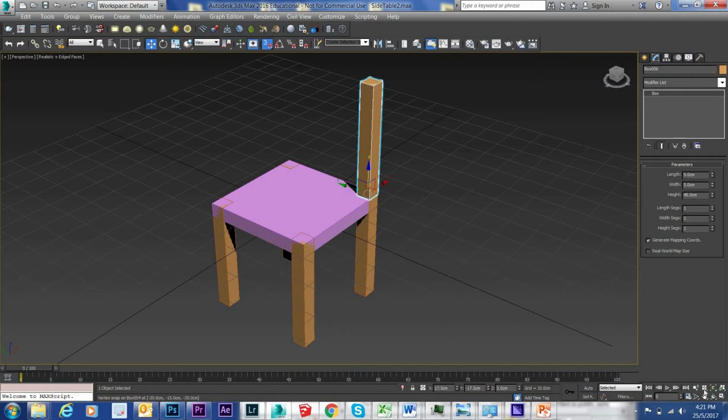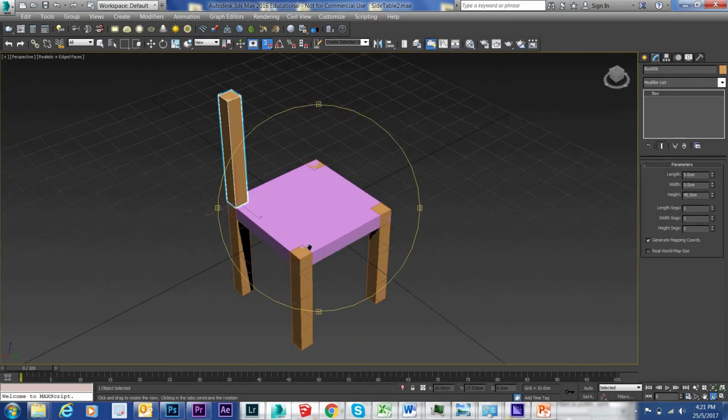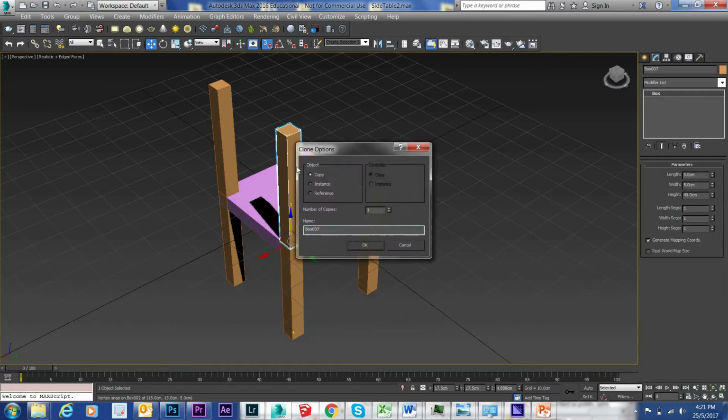And to do the other one, let's just spin this around, see it from the other side. Exactly the same process. We want to hold down the Shift, constrained on Z axis, and using snap with vertex, that should find the correct place.